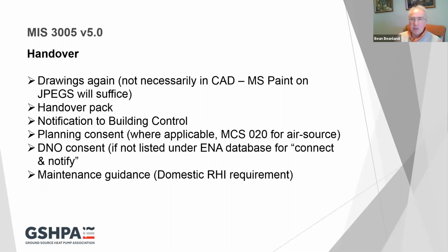And I know there are one or two manufacturers who say actually no maintenance required, but I think most of us in the industry would say absolutely not. We should certainly be looking at filters. We should be looking at error code histories in the controllers. We should be looking at the thermal transfer fluid. There's a whole load of routine checks that should be looked through.